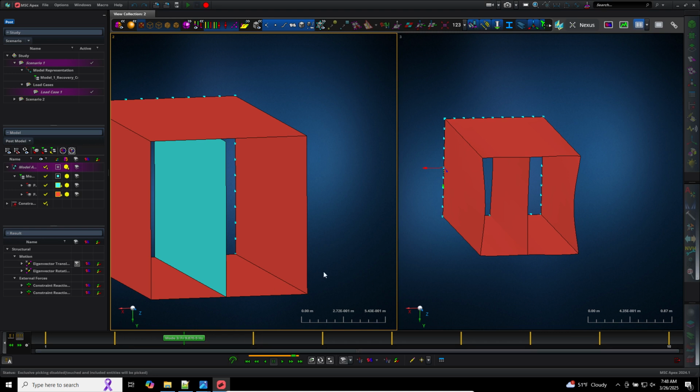It's a mechanism. So here on the left, this piece, since it's not attached, it's not supported, it's able to just move without deforming. That's what's causing the problem. More specifically, you cannot find the inverse of the stiffness matrix.